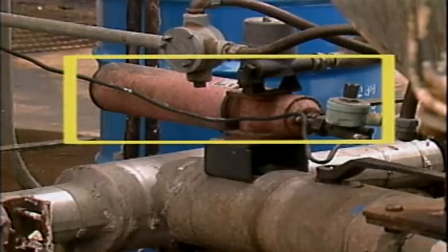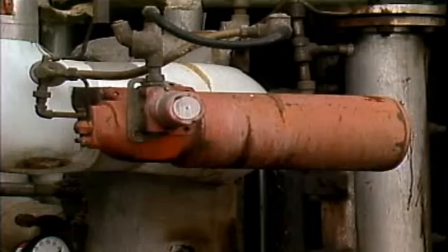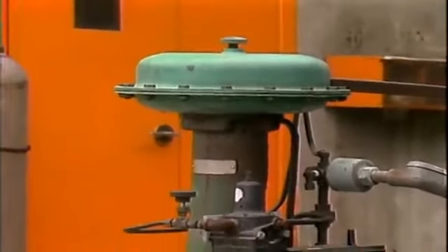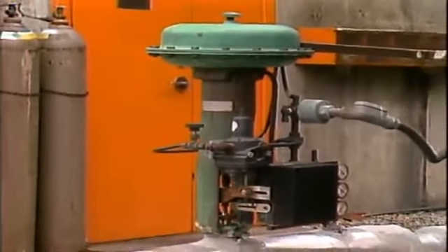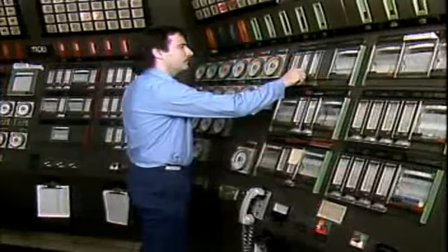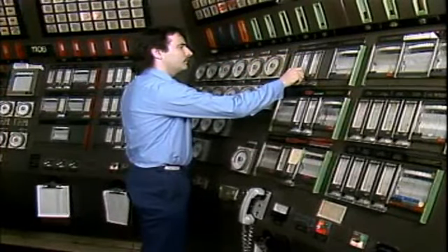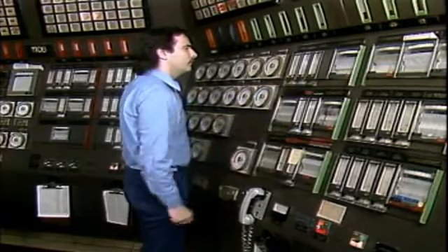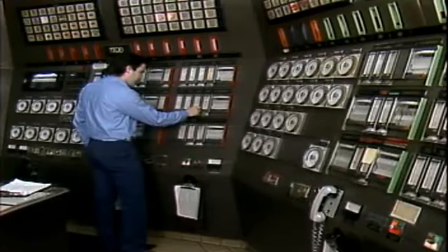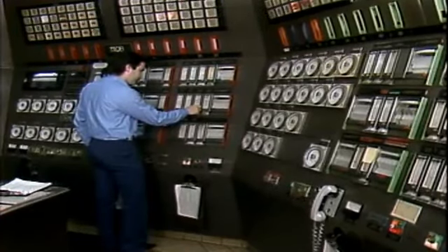actuators are used to position the valves. We'll define an actuator as a mechanism that moves or controls a device such as a valve. Actuators reduce the need for operators to go to every valve that needs repositioning and operate the valve by hand. When actuators are used, valves can be repositioned from a central remote location, such as a control room. This is very important in processes where a number of valves have to be repositioned accurately and quickly.